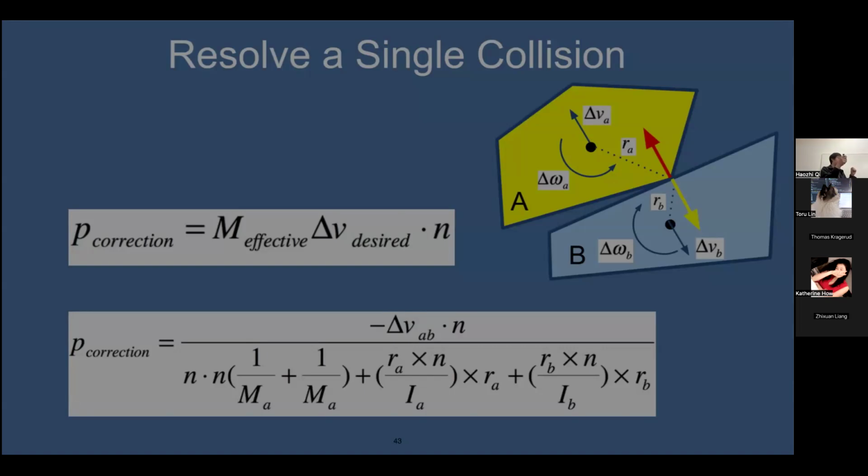So if you update the position and velocities and find there is some penetration between two different objects, what we could do is to apply some force, represented by the contact, that tries to move these two parts away. So at the contact point, we can apply the impulse according to how much the two objects penetrate, and then what is the velocity between the two objects.